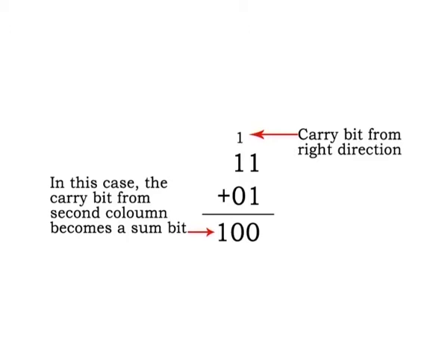When one binary number is added to another, each column generates a sum bit and a 1 or 0 carry bit to the next column to the left with 2-bit numbers. To add two binary numbers, a full adder is required for each bit in the number.